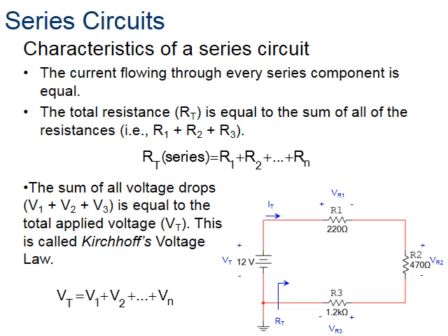And as we go around clockwise to the right, we see the first resistor, R1, has a value of 220 ohms, and the one on the right, R2, has 470 ohms. And then finally, the third value, R3, is 1.2 kilo ohms, K being 1,000. So 1.2 kilo ohms is 1,200 ohms.